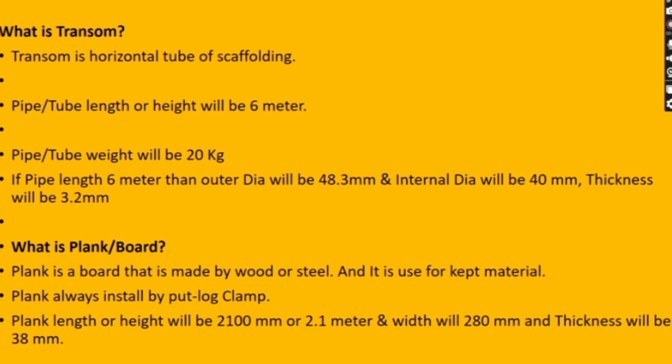And plank is always installed with lock clamps. Plank length will be 2100 mm or 2.1 meter, width will be 280 mm and thickness will be 38 mm.